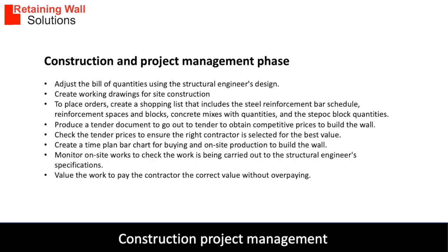Construction and project management phase. Adjust the bill of quantities using the structural engineer's design. Create a working drawing for site construction. To place orders, create a shopping list that includes the steel reinforcement bar schedule, reinforcement spaces and blocks, concrete mixes with quantities and the step-up block quantities.